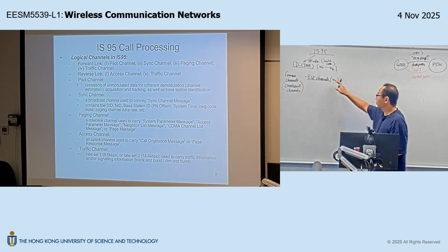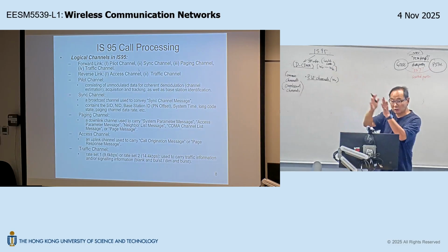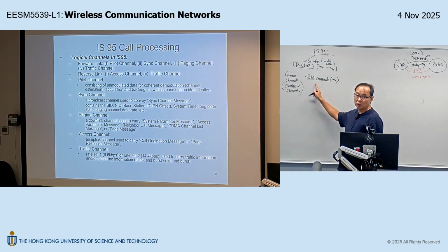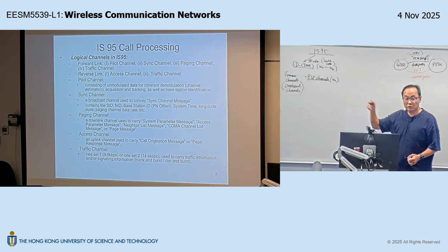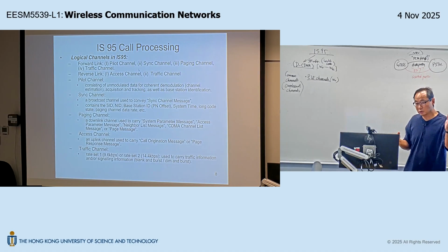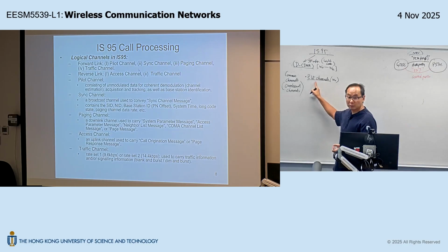This W0 up to W63, 64 Walsh codes, are all defined in the standard. Each label has a specific pattern. So this is the first overhead channel, and we have explained the reason for transmitting this channel: it is a timing reference for mobiles to search the possible despreading timing. It carries no information. There is no information from this channel. It is just like a beacon.